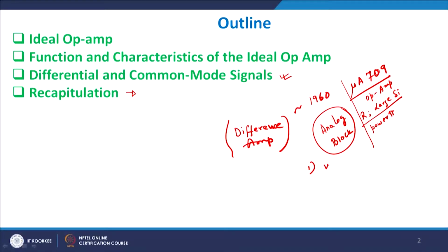The reason it is so versatile is that you can put this operational amplifier anywhere within the structure wherever you have an analog signal, or for that matter even a digital signal, but primarily in 90% of the cases analog signals. You can do a large amount of computation in the analog domain using an operational amplifier. So you can add two signals, subtract two signals, multiply two signals, cascade signals, and so on and so forth.